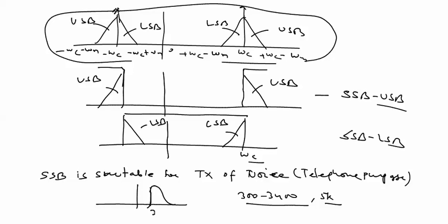roughly 300 to 3400 Hz, and the same on the negative side, an exact replica. The bandwidth is considered from the positive side only. If we use the filter method, the filter is not ideal, it is practical. Some initial spectral gap is there where the filter suppresses the initial components of the message, also in the negative side. But we have no important components in 0 to 300, so practically this transition from 0 to 300 does not affect the quality of voice, so it is the best suited method for voice transmission.